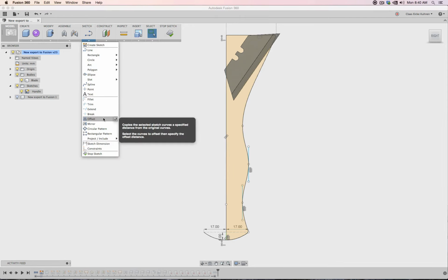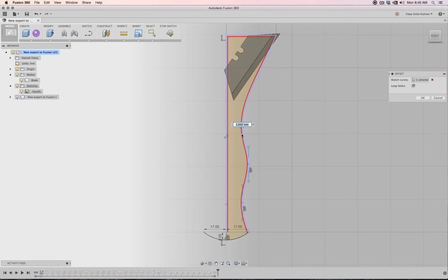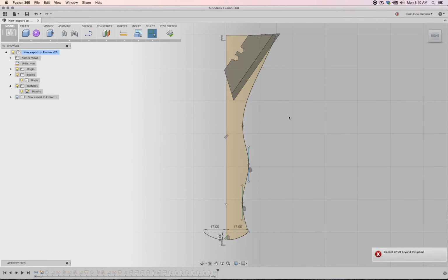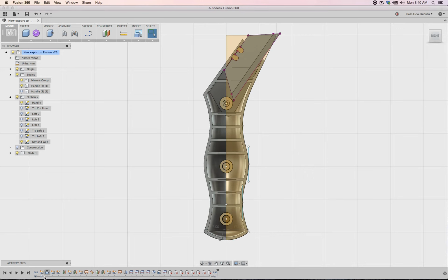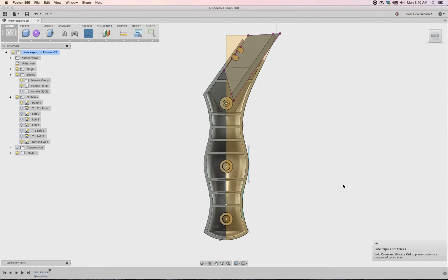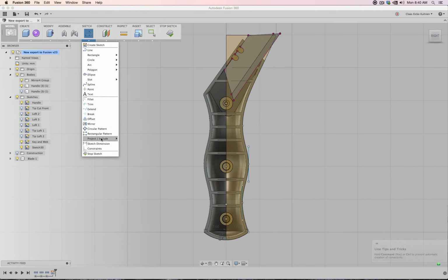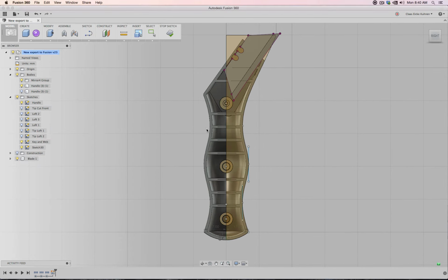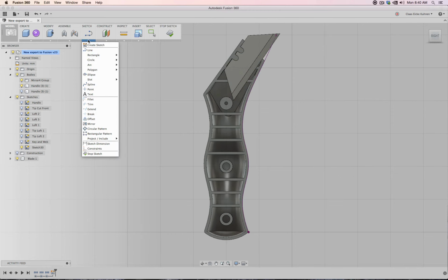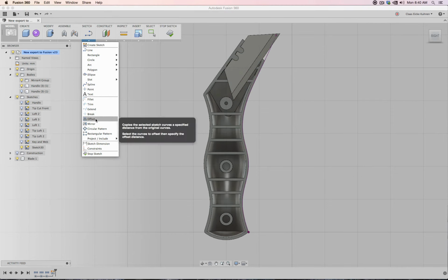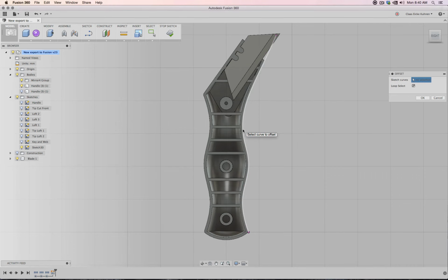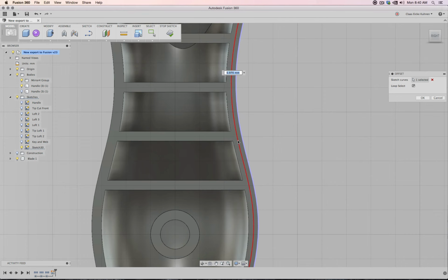And I'm going to use the offset of this line here, and no, that's not the way I'm going to do it. I'm not putting that into there actually. You know what I'm going to do? Stop sketch. This will take a second because it has to update everything. I simply will create myself a new sketch here and project this edge there. Then I can hide this one. So I just made a copy of it into this new sketch, and then this included sketch I can then offset. And let's say maybe 1 millimeter.